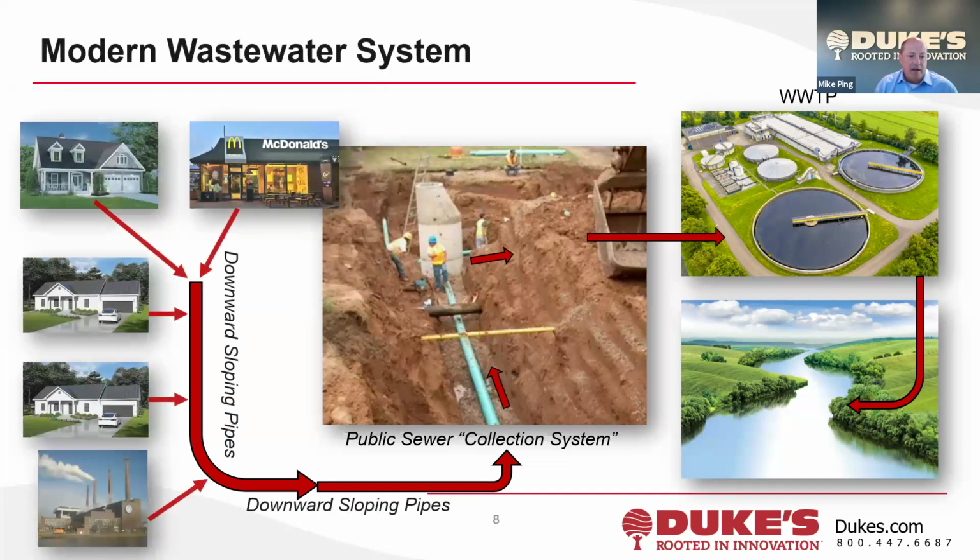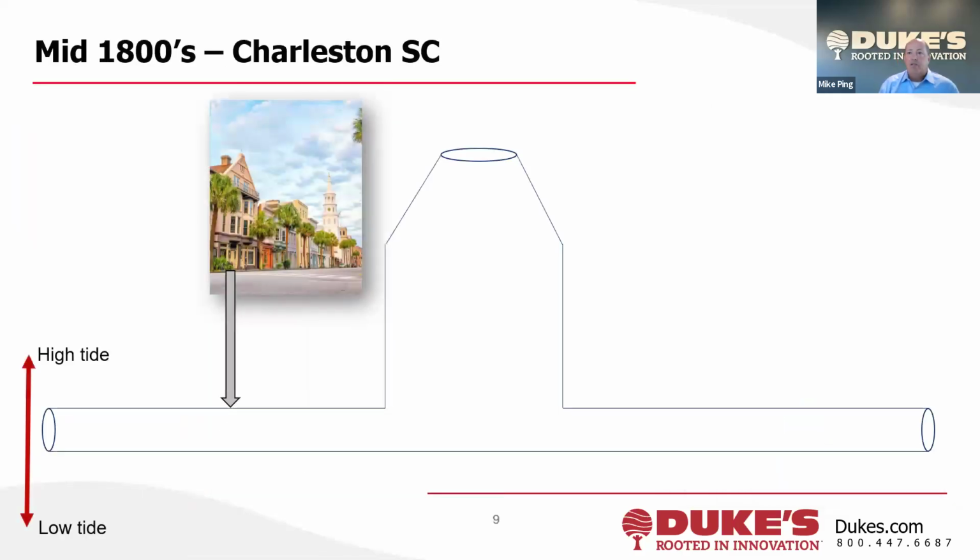And then finally, kind of replacing the old Roman bathroom, modern day users of wastewater: restaurants, bottom left, industrial, residential homes, etc. They have what's called a service lateral that goes out to the main sanitary, the public system, and goes all down the hill, so to speak, through manholes onto the wastewater treatment plant and finally to the receiving water.